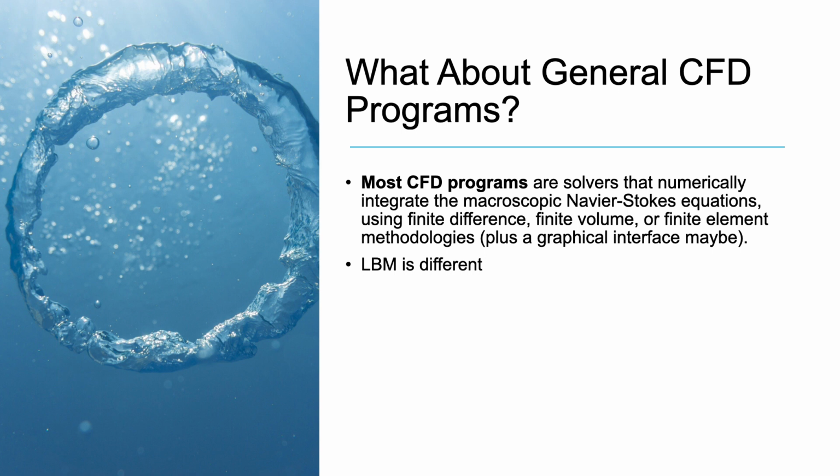So what about general CFD programs? Well, most CFD programs that you will find out there are solvers that are numerically integrating the Navier-Stokes equation, which are macroscopic equations. And then they use some methods that can be finite difference, finite volume, or finite element methods, and of course a graphical interface to solve all of that. But LBM is different, and we'll see why.